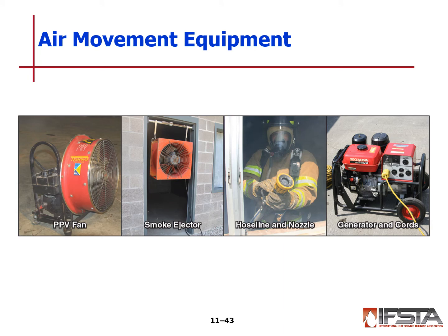The positive pressure fan here is typically what we carry. It's gasoline operated, and what we have to realize with this piece of equipment is it's designed to run on a gasoline operated internal combustion engine, so it does produce carbon monoxide and it is blowing that exhaust in. So there comes a point when we either want to use electric or we want to change this over to electric and get the rest of the carbon monoxide out as well.